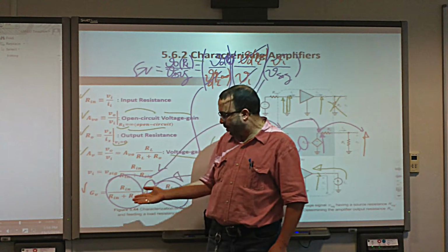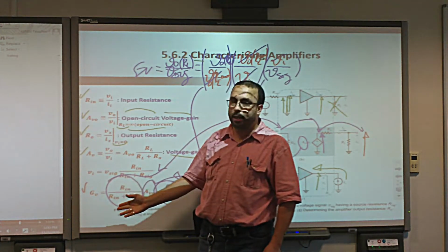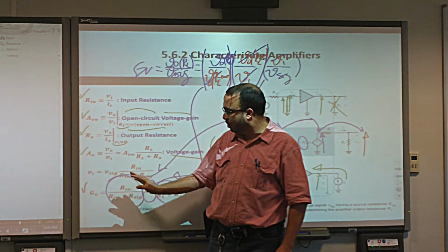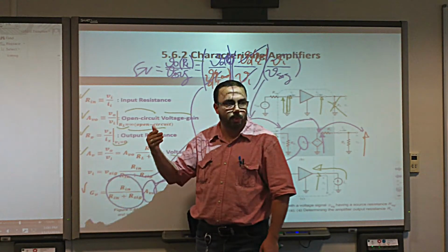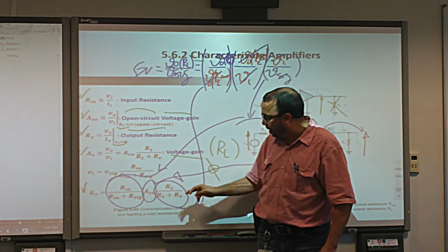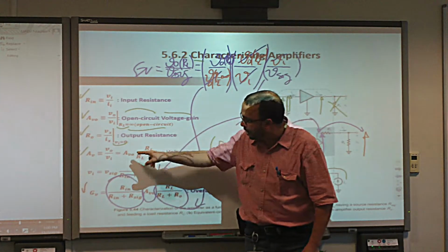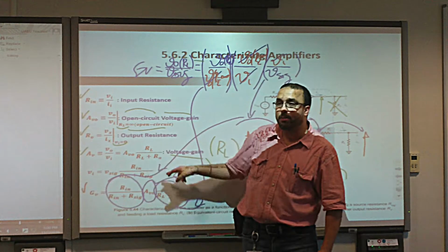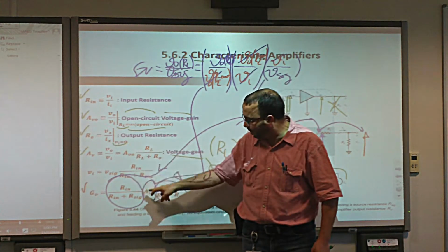1. Thank you very much. So this will become 1 when Rn is so high or infinity, yes or no? Boom, this is going to be 1, so we can throw it away. So what remains is Av0 RL divided by RL plus R0. Is it the same expression for the voltage gain, yes or no? It's the same. Av0, Av0.